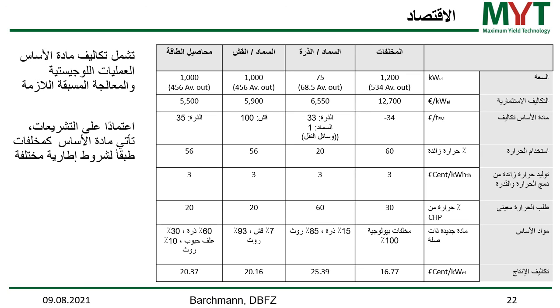If you compare liquid manure, which you can, if you build the biogas plant right on site of a dairy facility, for instance, you can feed your process directly with a simple pump. If you have, compared to that, waste materials, you have to pre-treat that. You have to separate out disturbing materials. You have to remove plastic, stones, things like that. And that's of course more costly.